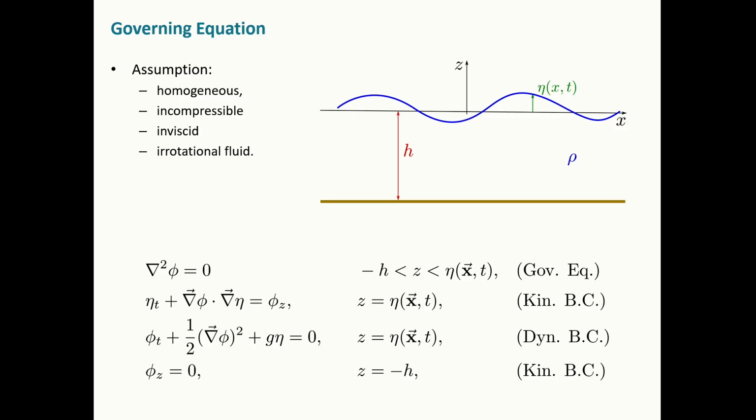So just briefly about the science, I just point you to the complications that we face. The governing equation is Navier-Stokes, but that's very complex. So we make simplifying assumptions. The water is homogeneous, a very good assumption for tsunamis, incompressible, inviscid, irrotational. The governing equation becomes Laplace's equation with a bunch of boundary conditions. This is the simplest imaginable partial differential equation in the world. Linear, second order, but that doesn't matter. The complication comes from boundary conditions.